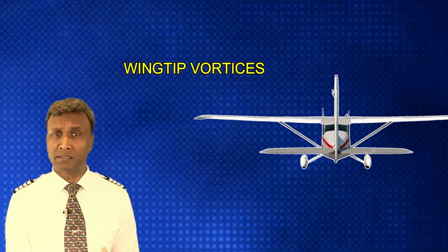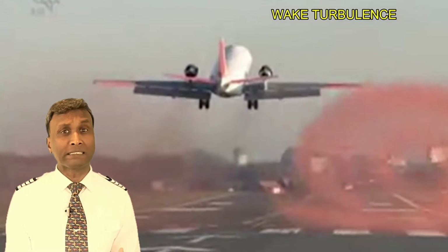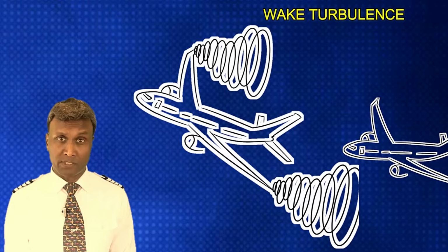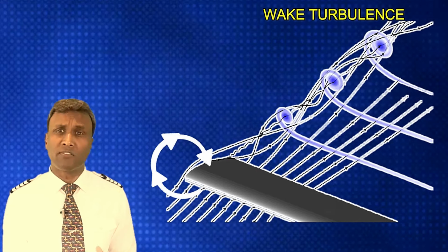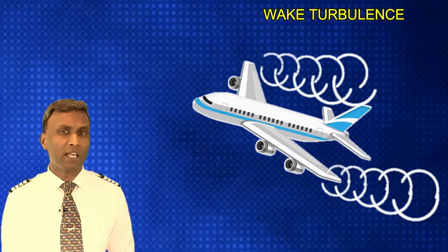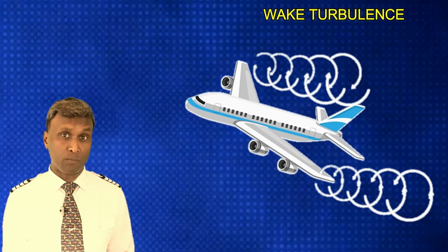These vortices persist in the aircraft's wake, called wake turbulence, which poses a significant consideration for pilots. Pilots must maintain a safe distance from the aircraft ahead to avoid encountering the turbulence generated by these vortices. The strength of wake turbulence varies based on factors such as aircraft weight and configuration. Heavy aircraft tend to produce stronger vortices, leading to more potent wake turbulence.